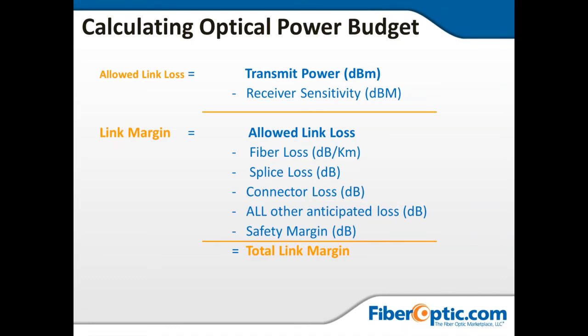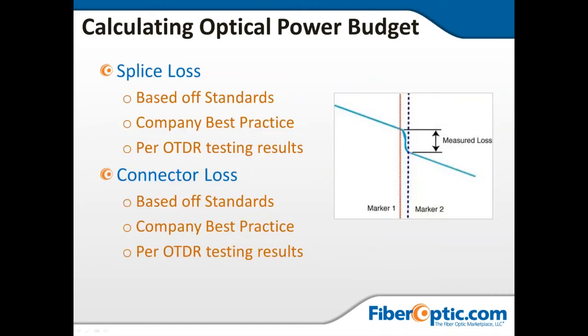If it loses so much, and this is an old copper signal-to-noise ratio, there is no signal for the receiver to see, and your system literally does not work. But it could have different problems associated with it if you're too close, and that's the idea of the safety margin, to allow for physical things, even defects that maybe the installer might make, like too tight a bend, for instance. But you can easily calculate what we call the optical power budget.